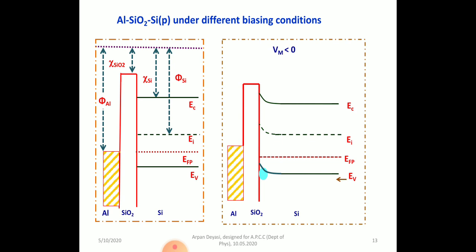So at this condition, you are also bending the insulator band diagram. The question will be why? Now think. At that point, insulator band will be bent in such a way that in the metal side it will be higher and the semiconductor side it will be lower.